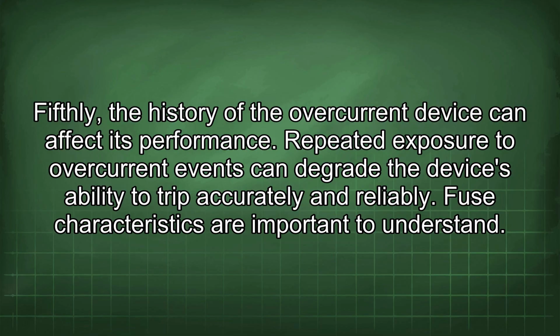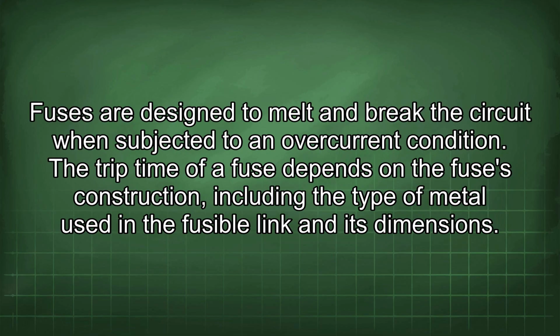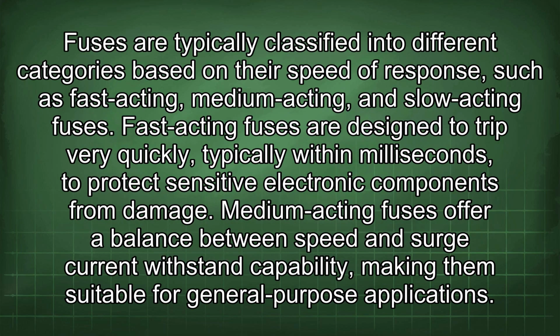Fuse characteristics are important to understand. Fuses are designed to melt and break the circuit when subjected to an overcurrent condition. The trip time of a fuse depends on the fuse's construction, including the type of metal used in the fusible link and its dimensions. Fuses are typically classified into different categories based on their speed of response, such as fast-acting, medium-acting, and slow-acting fuses.